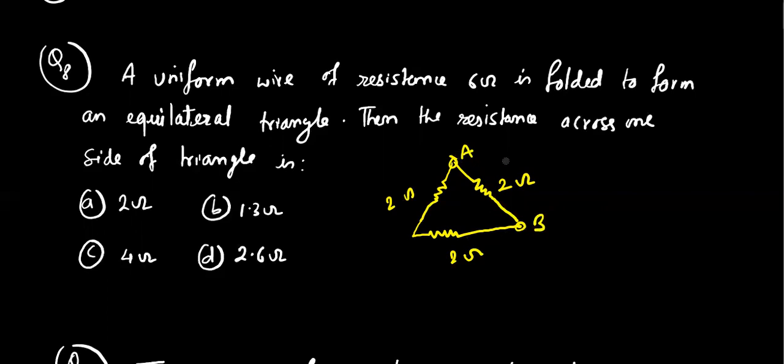Okay, so if we analyze from this side, we can easily see here, suppose this is C, the resistance from A, C, B is in series, and the series combination is connected in parallel with this 2 ohm resistance. That's why we can easily say that the equivalent circuit will be like this one.